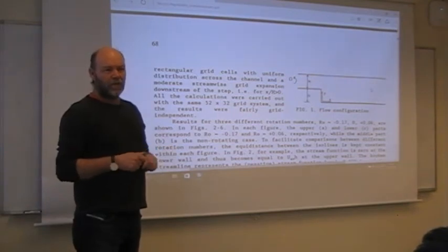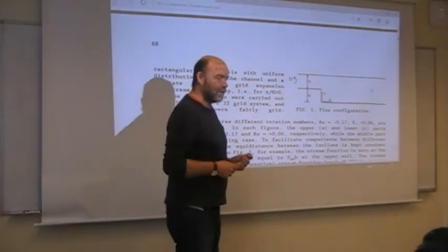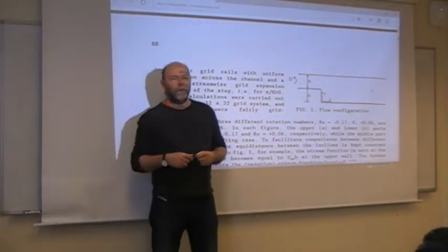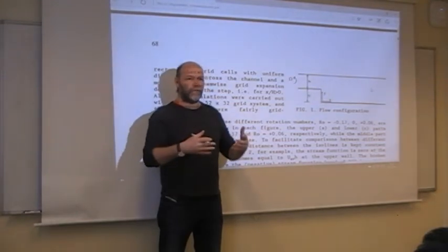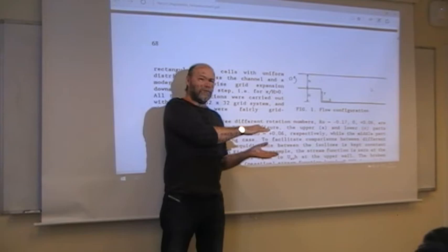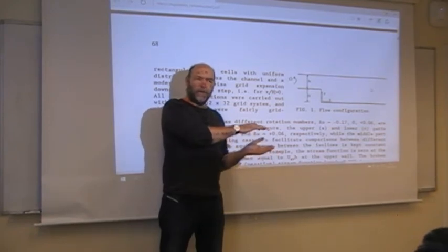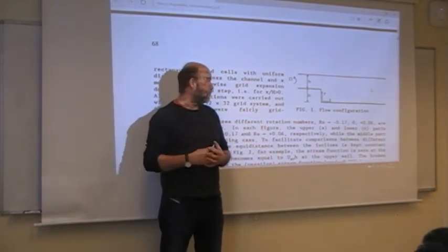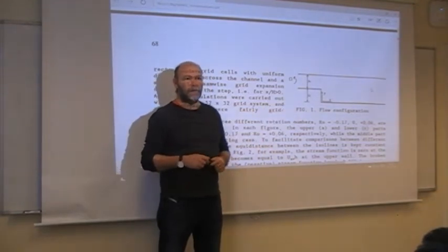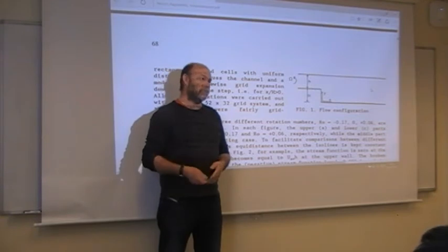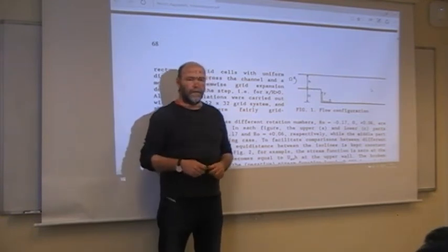According to theory, we should have received what we call a grid-independent solution. So you simulate with finer and finer mesh until you see the solution doesn't change anymore. Then you are very happy. Then you have a grid-independent solution. That's not possible with turbulent flow, k-epsilon model. Every time you change the mesh, you get a totally different solution. So it's a real pain, to say the least.